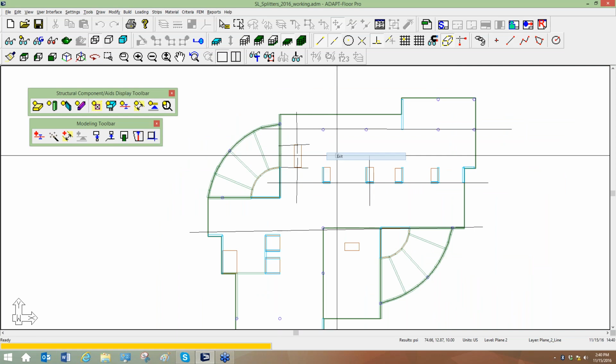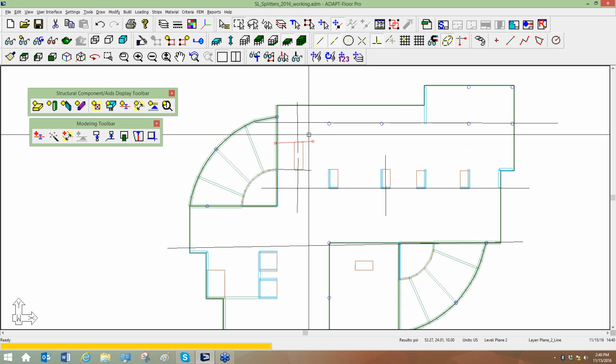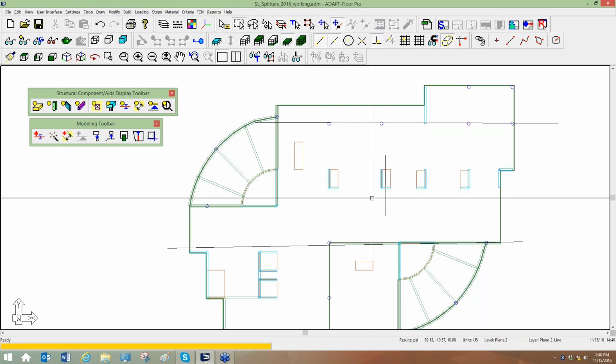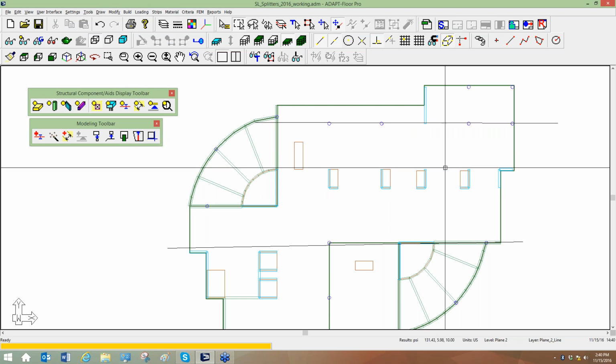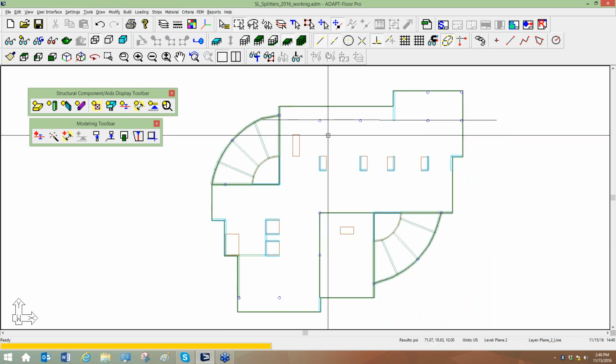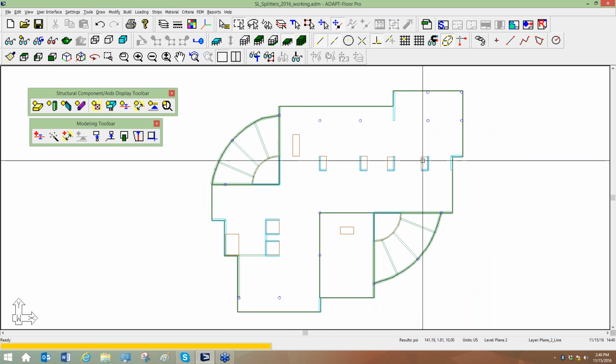Okay, now some users want to see no cuts extending into openings. So for this example we will place splitters around all openings so we can try and get a situation where we have no opening with tributary region extended into it.